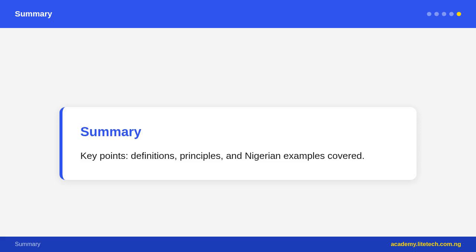Plus slabs, floors plus roofs, flat horizontal plate structures. Plus frame structure, skeleton of columns plus beams, steel or reinforced concrete, very common for multi-story buildings. Plus load-bearing wall structure, walls carry loads directly, common for smaller low-rise buildings.